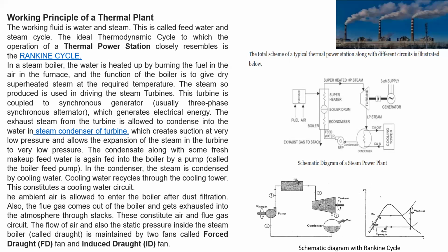So this is the short version. After conversion from heat energy to mechanical energy, the steam coming out of the turbine is condensed in the condenser. The purpose of condensing is to cool. Why cool? Because this water is special water. That water is reutilized with the help of a pump to the boiler, where this water is again converted into steam. This is the Rankine cycle; at present you don't need to go through it.